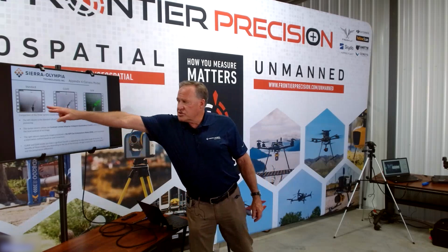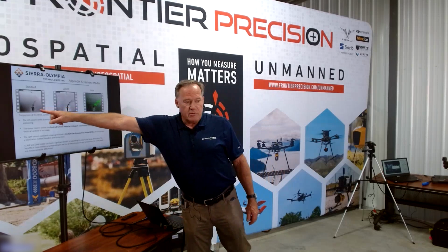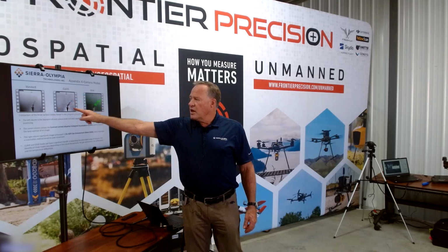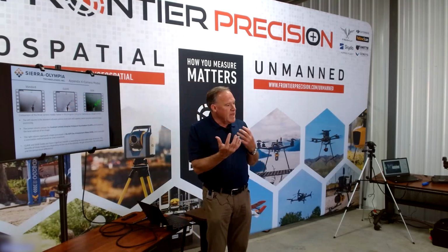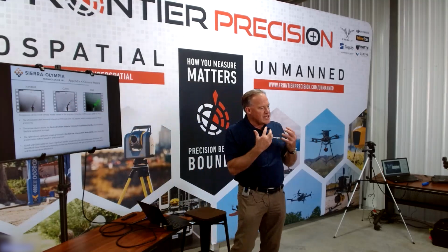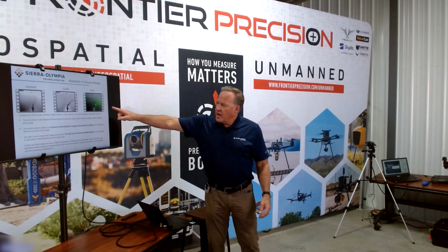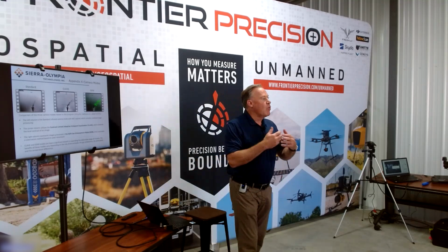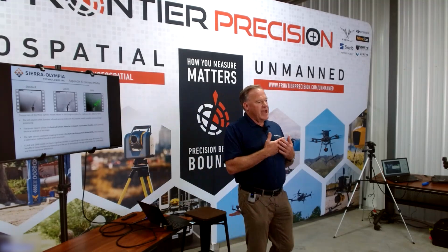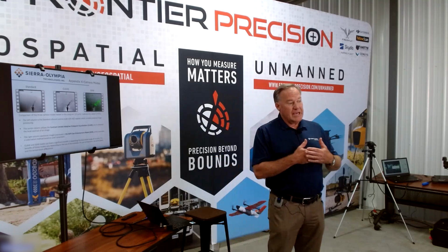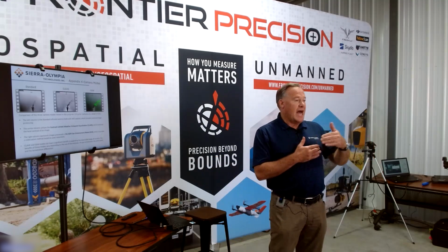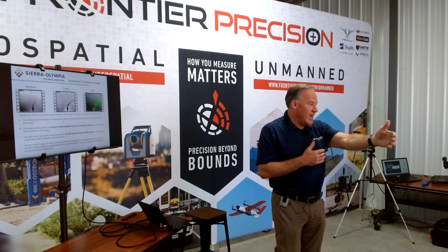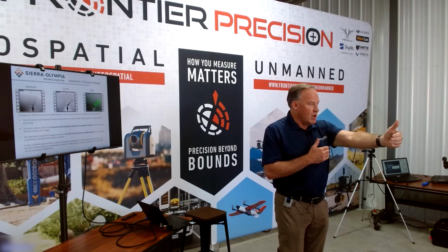This is where we use the standard AGC mode. That's what the image looked like. Now notice the same image, but in high-gain mode, it looks a lot better because there's more contrast and edge adjustment. And then when you use the GEM mode, the gas enhancement mode, it's even more visible. And what we found is the GEM mode, in many cases, in some cases, allowed us to visualize that same leak twice as far as it would if there was no GEM mode on.